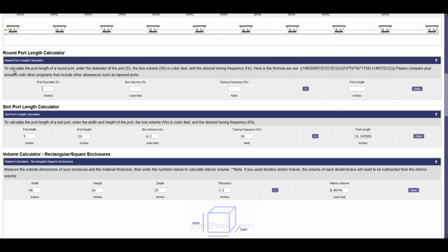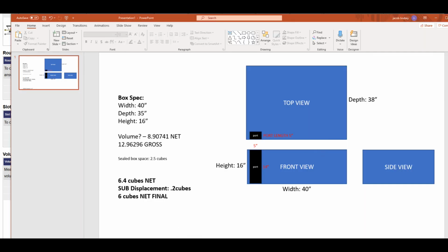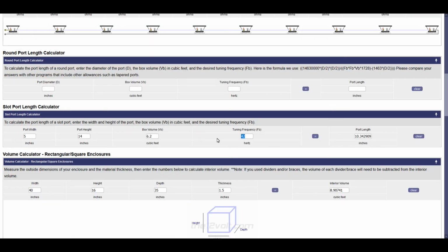It's not going to be 100% accurate, but I'm sure it's within 85 to 90%. I know for sure because right now, for example, my box is tuned at, what did it say, I was tuned at 47 hertz, I think it was. Yep. So I'm tuned right around 48 hertz, but I'm peaking at 45, 46 hertz. So it's within 2 to 3 hertz of my frequency range. But it also depends on your peak resonance and how your vehicle reacts to it for your port adjustment.